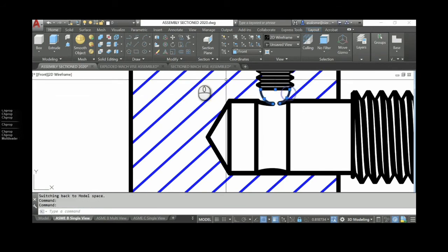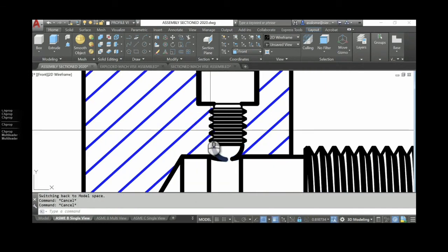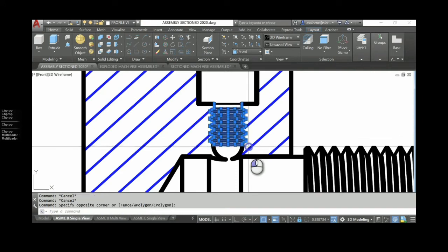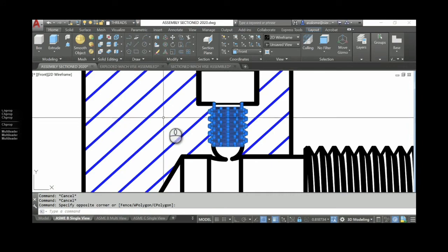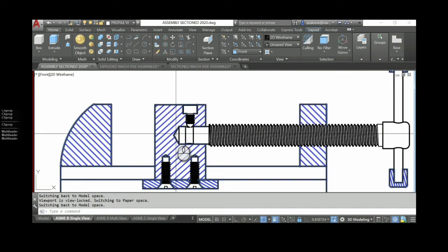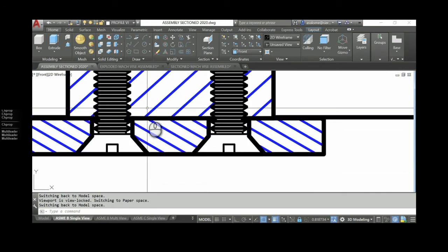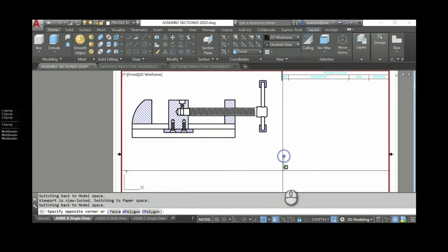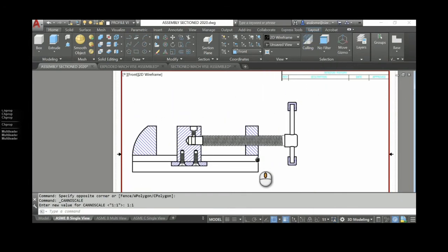So that when you print that, it should look good. These are going to profile viz, and the actual threads are going to go onto that thread layer. Okay, and so you're going to work these through. You're going to get these all adjusted so that this all looks good. And then I set this viewport up at 1:1. It fits nicely on here.